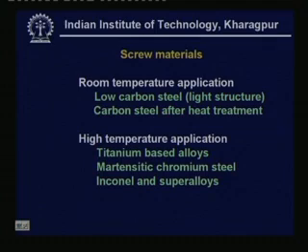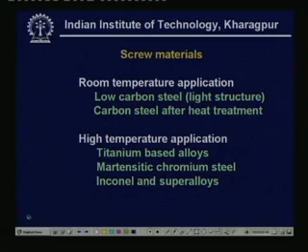Now the design will definitely depend on the material selected for the fasteners. So what you are seeing is a list of the screw materials. Now the screw materials will be chosen depending on the application temperature. For room temperature applications, the materials are low carbon steel, this is for the light structure, and maybe medium carbon steel, but it must be heat treated.